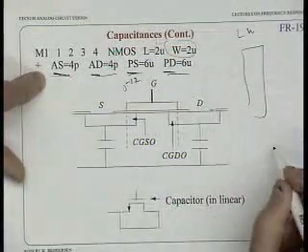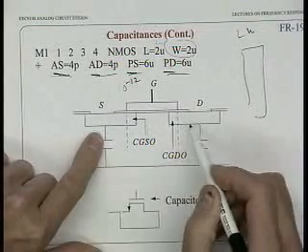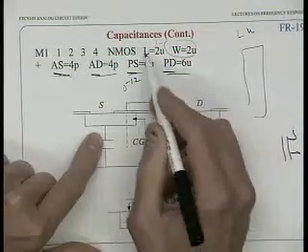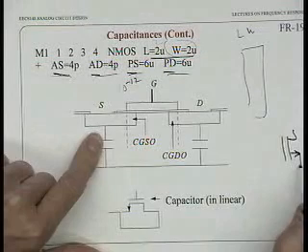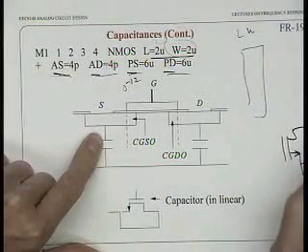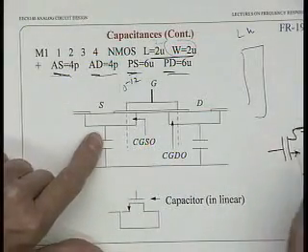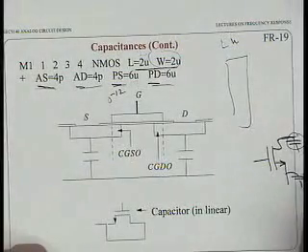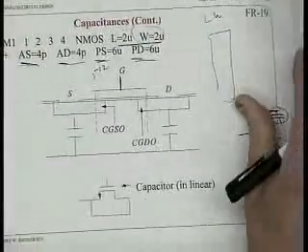These are all used for the parasitic drain and source capacitances, right? The gate capacitance is calculated from the W over L itself, so you'll get the gate capacitance correctly, but what you won't get are these little junction capacitances on the source and drain, that are pretty important when you talk about the inverter output stage that you have. So they come into the calculation here as we showed in the notes last time. So that's point one.